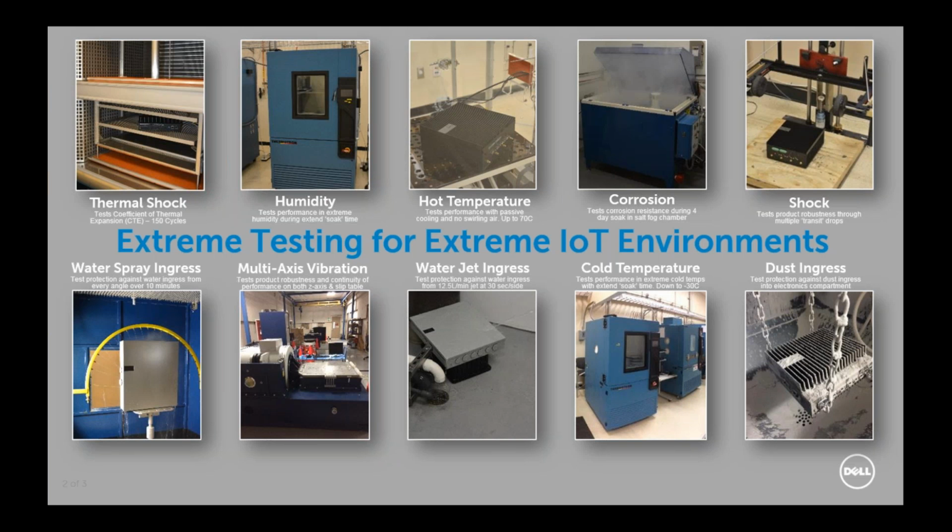But even beyond that, when they test the whole assembly, they'll do it in a chamber where there's airflow. And in a lot of situations, you're going to put these boxes into control cabinets or places where it's dead air. So we test our products with dead air, no movement, and no airflow at all. And we test it with all the buses and the processor all running at 100%, so that we know it's not dependent on that specific use case. Whatever the constraints are within that high temperature range, we can withstand that, and we can guarantee that our products will be able to make it through that extreme environment.